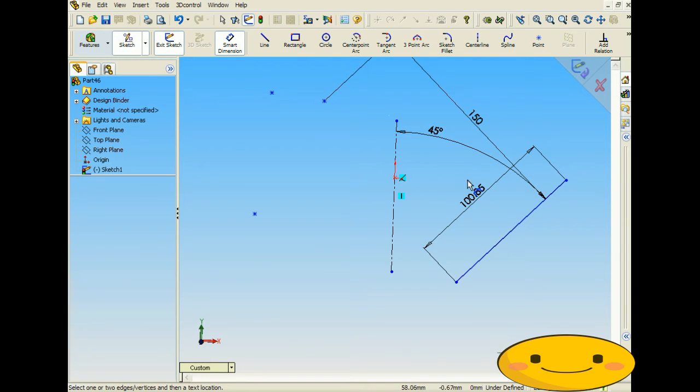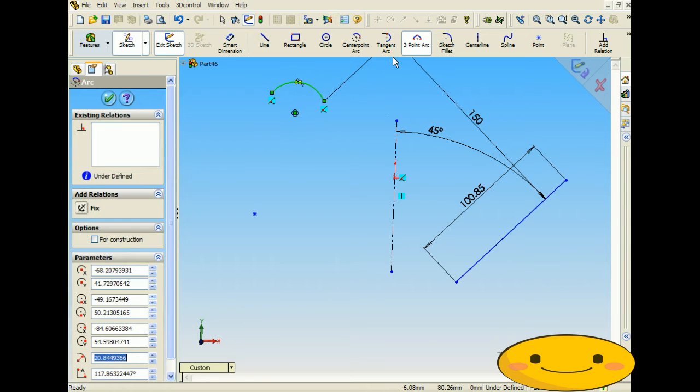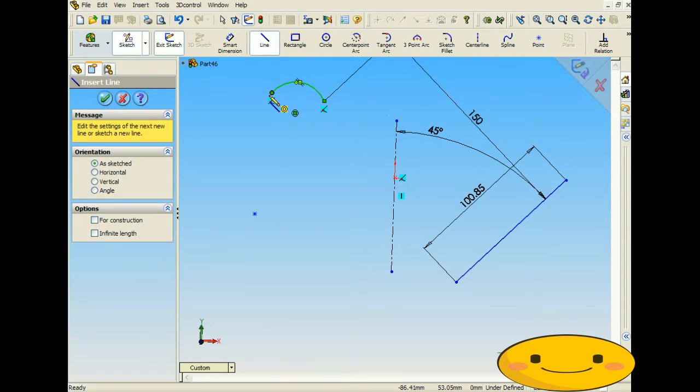So even though this dimension is already kind of pushed there, say we threw in some points and it already had constraints on it, we can use those points then to constrain the rest of the sketch. And then say we like our points and the positions that they're in, then you can go and fill it out and say, let's close that one up there, and we want a couple lines here.